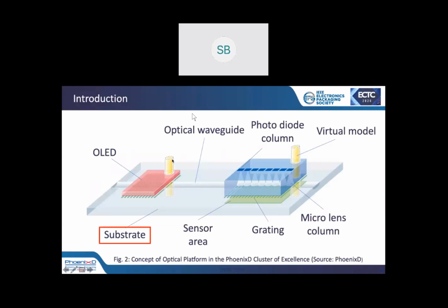The injection molding is not an easy process in this case. We have a lot of challenges to handle, for example, the planarity. The planarity of the substrate is a big issue. Therefore, we had to work on the material parameters and the injection mold parameters. After several DOEs, we could create planar and very good specimens, which have a high surface planarity.